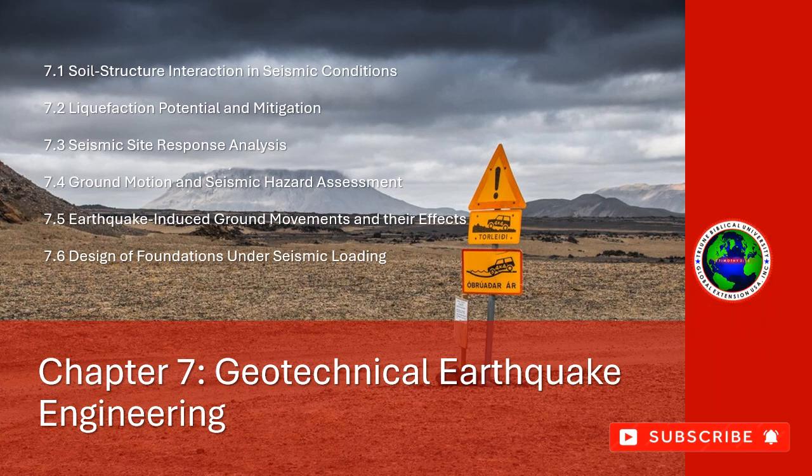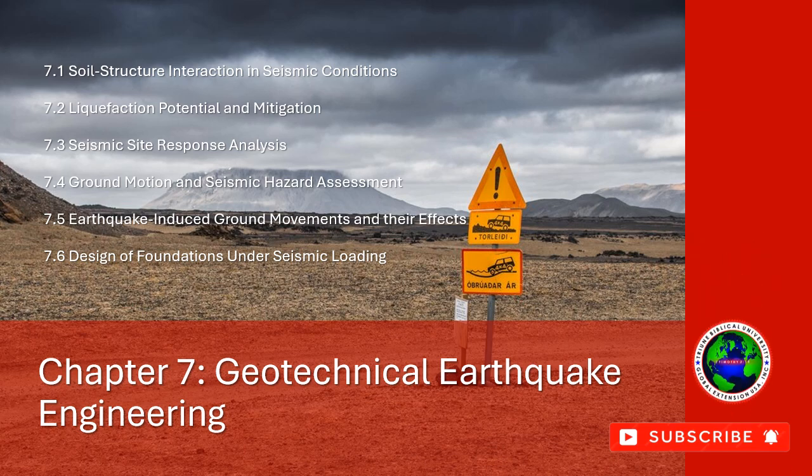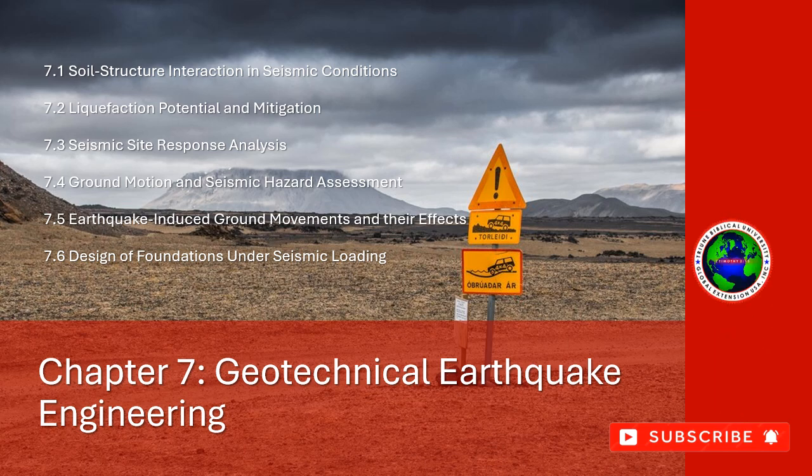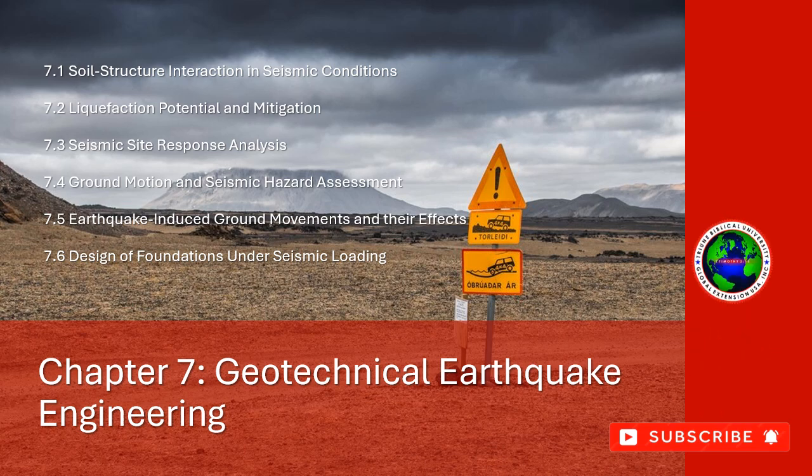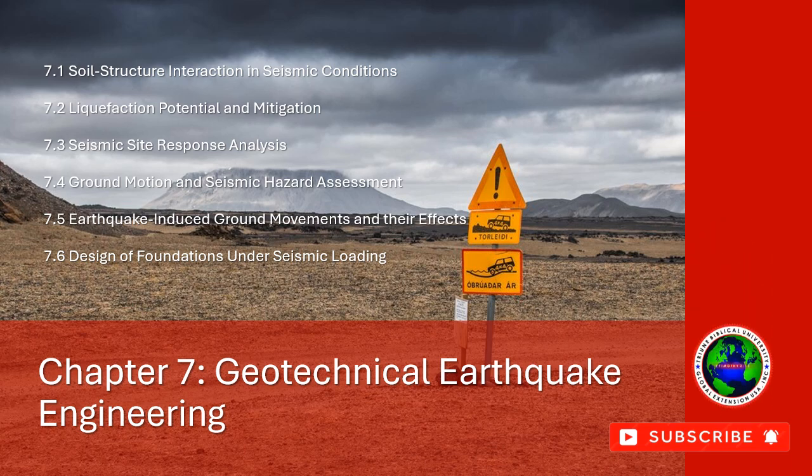7.2.2 Factors affecting liquefaction potential. Several factors influence the likelihood and severity of liquefaction during an earthquake, including soil properties, the intensity of ground shaking, and groundwater conditions. 1. Soil type and particle size distribution. Loose sands and silts are more prone to liquefaction than dense or cemented soils.